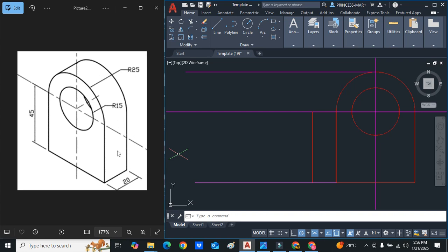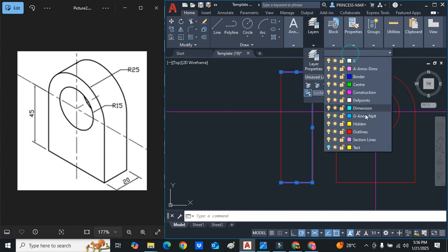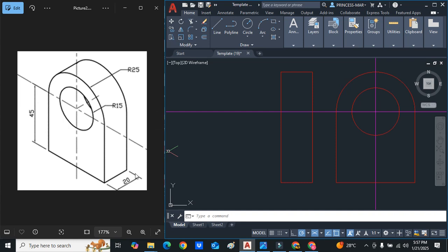So if you look at this curve, it might look curved from the isometric view, but if we had to turn the object to a side, it will look like a straight rectangle. So this piece would come straight up, and now the width here is 20, so we offset 20, and I'm just going to trim to clean it up. So here is our end view. This is a view that we're looking at from the smaller side here.